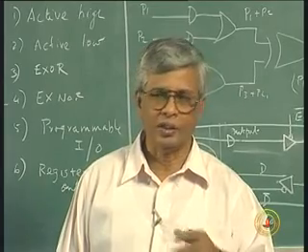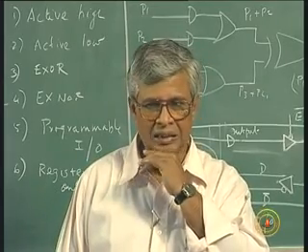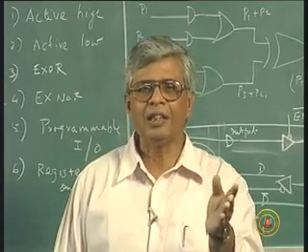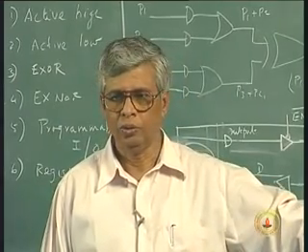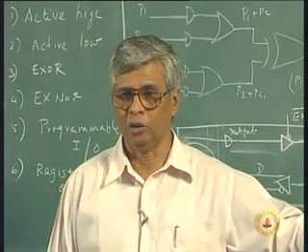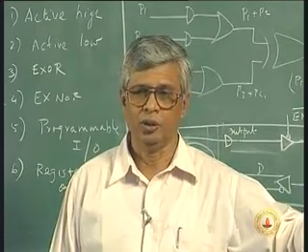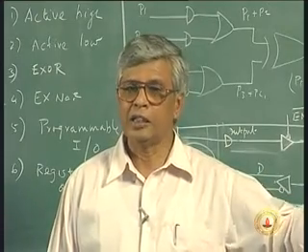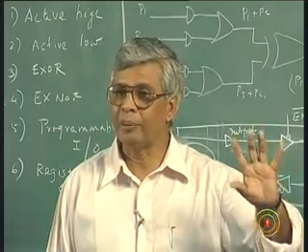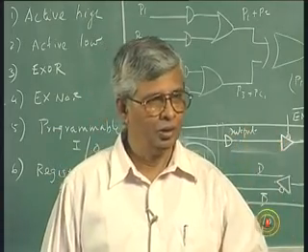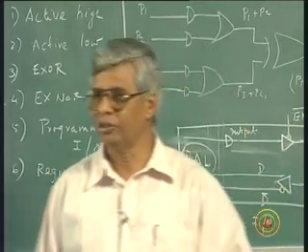Most of them have this. Mano has it. So you look at a 16R8 diagram, it will become clear. Registered outputs, or you can look for 16R4 also, 4 registered outputs. Since it is 16R4, up to 16 inputs and 4 registered outputs, which means the other 4 can be non-registered outputs. 16R4 if you want is enough.